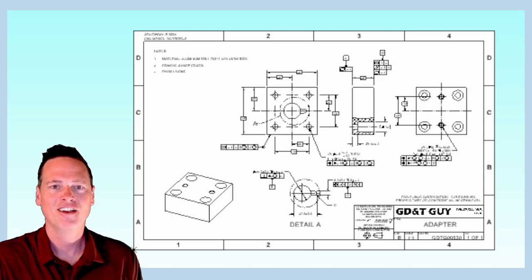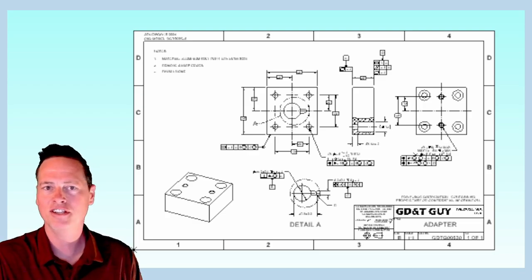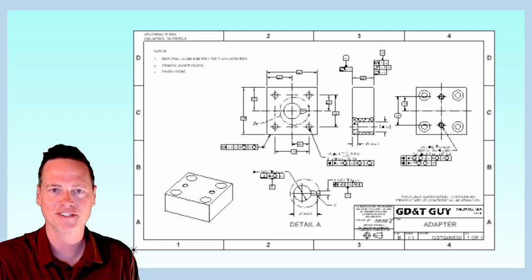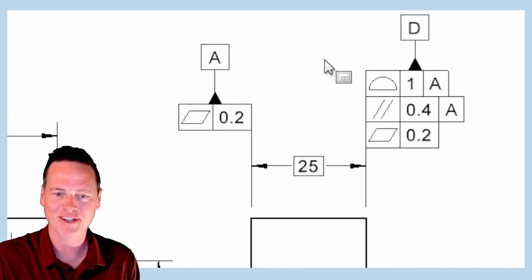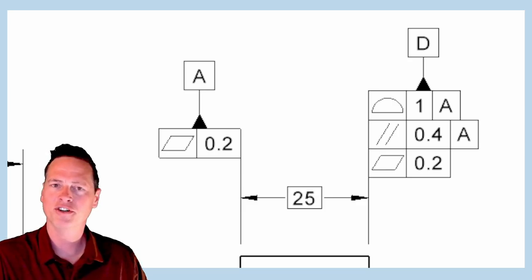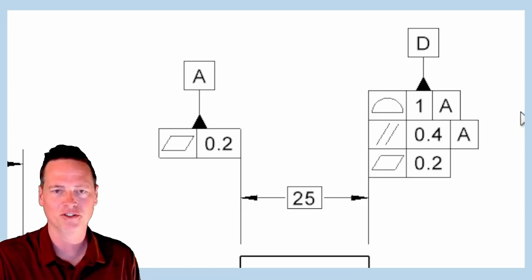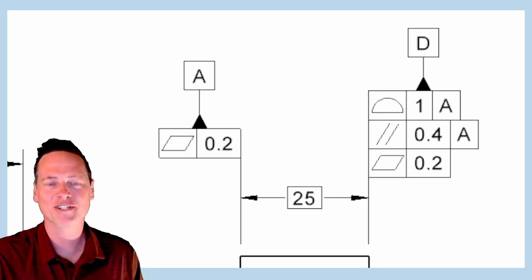Okay, so I've showed you the bad examples, but now let me show you the way I think you should do this. And this is drawing GD&T 00530. You'll see that a lot of it's the same right up to this 25 millimeter dimension. There are some improvements here. I went for a basic dimension. I added a positional, orientation, even flatness control to the datum D feature.